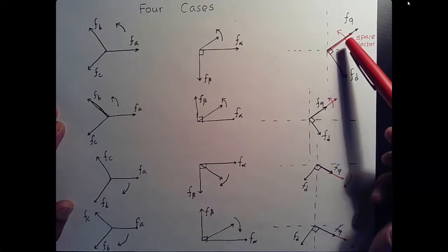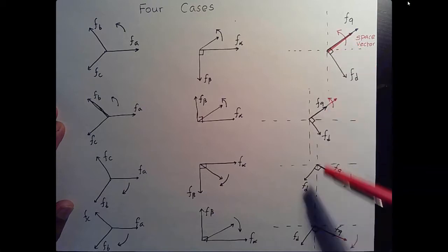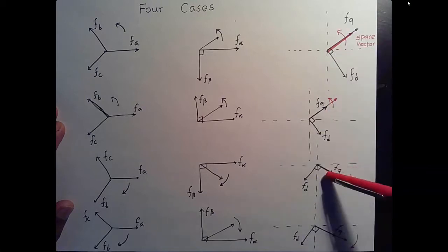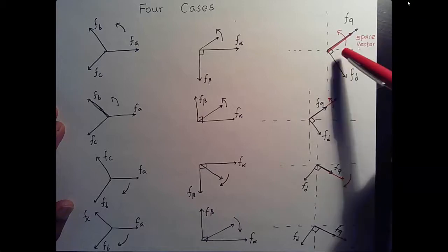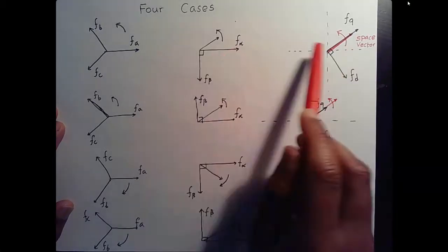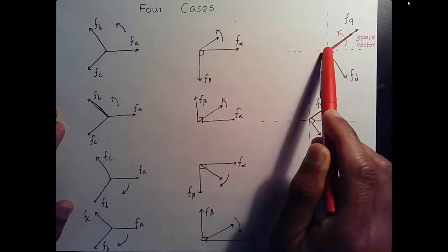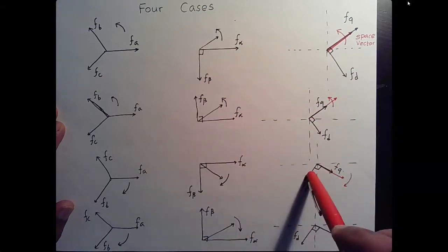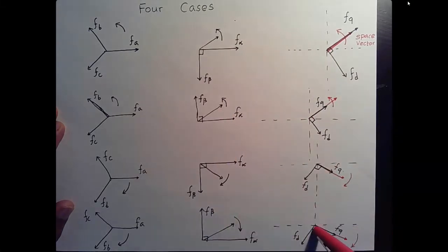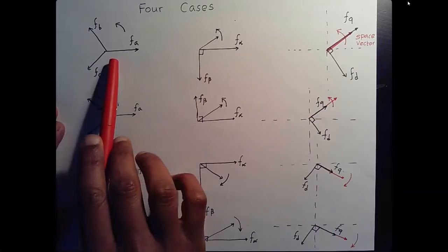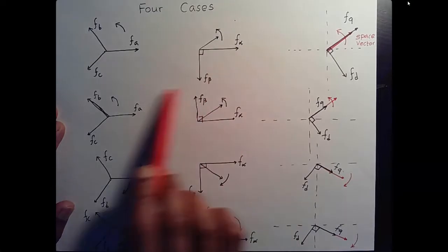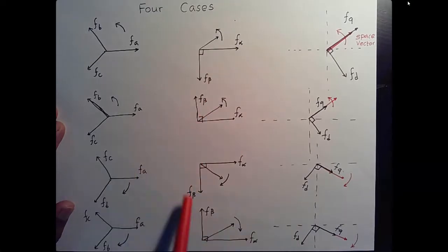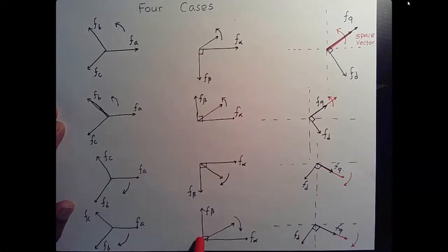Now, when you implement them, for you to get consistent results in doing the reference frame transformation, you need to accommodate the transformation equations to account for the different axis alignments. Going from ABC to alpha beta will change here versus here, and here versus here, so they're going to be different in each case.